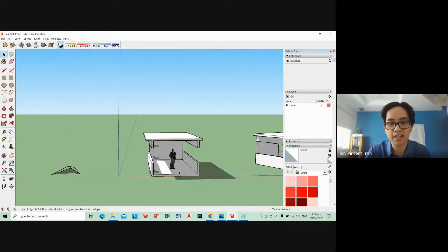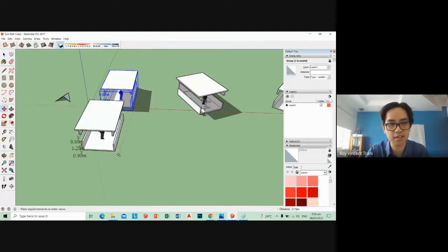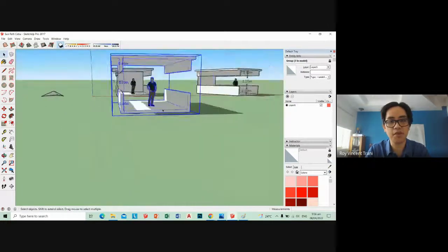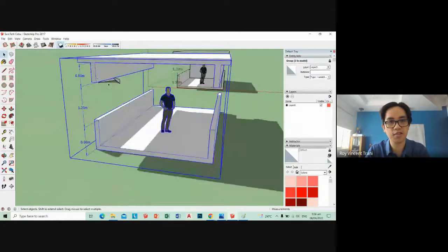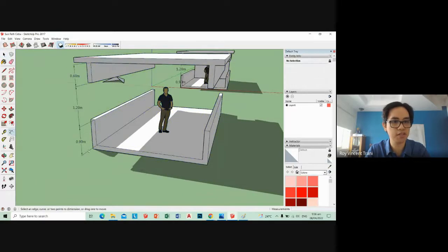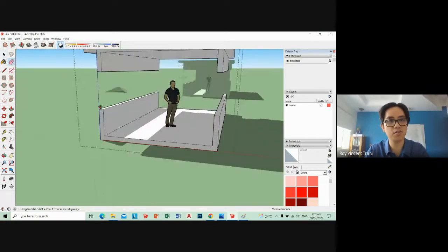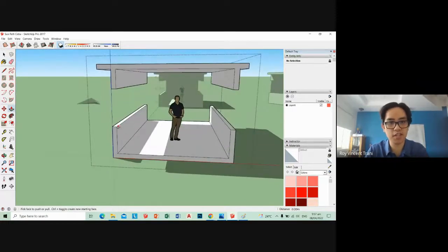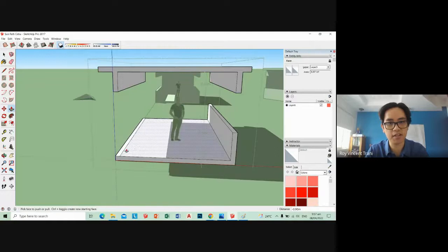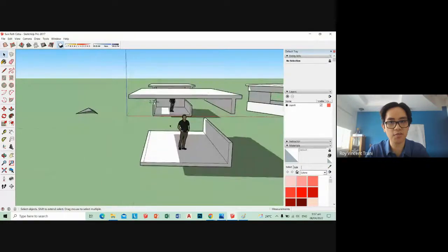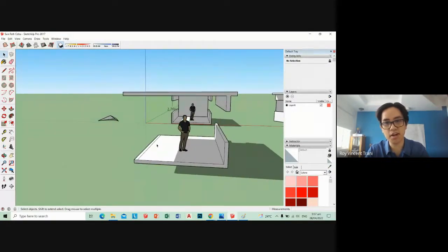And then let's discuss further the impact of your facade. If you want a full glass facade, if your total height here is 2.7, that's 0.9 plus 1.2 plus 0.6. Should be 2.7, let me double check. That is 2.7. So let's say you want to make your opening floor to ceiling. How much sun is coming in? You got that, and you got that. So I think almost the 0.9 is actually blocking a lot of sun.